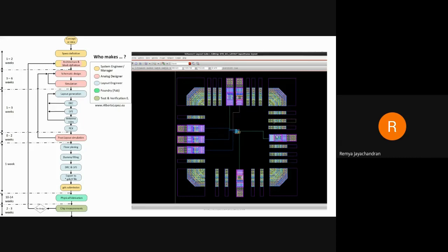So you have to place these IO pads in a proper position. The foundry will give you the dimensions of the complete IO pad frame. There will be standard sizes for that, the length and the width, and according to that, you have to create this frame. Here I have just shown that in between you can see the spaces are there. You have to fill them with filler pads. So again, you will get a complete IO pad frame, and inside that you can place this transistor and make the connections to these IO pads.